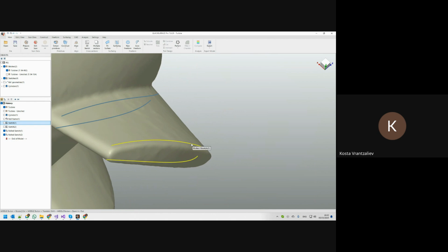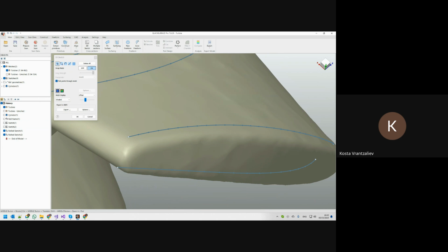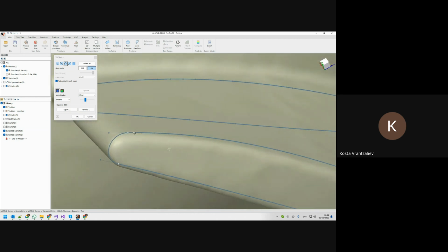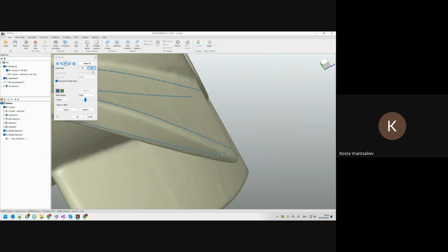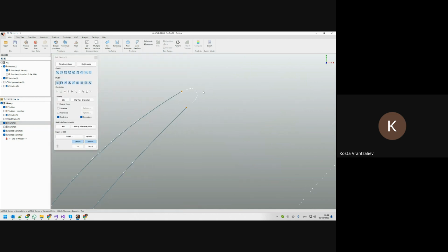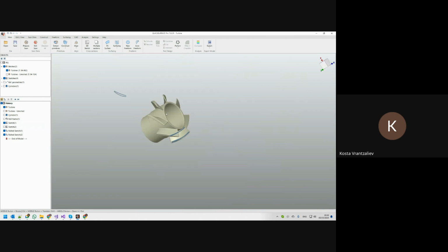And this is a 3D sketch. Of course, you can edit, and here you can add the blend curve. Okay, cool. Sorry, I just didn't do this correctly. So you can modify this if you want, and you can tweak and improve if you need to. But the other option, if you want to do the exercise yourself, to experiment, just go back to the 2D sketches, close it here with a nice transition, probably with a tangent arc, like this, and do this yourself, and then roll back in 3D, and you see what's going on. So this was one example.